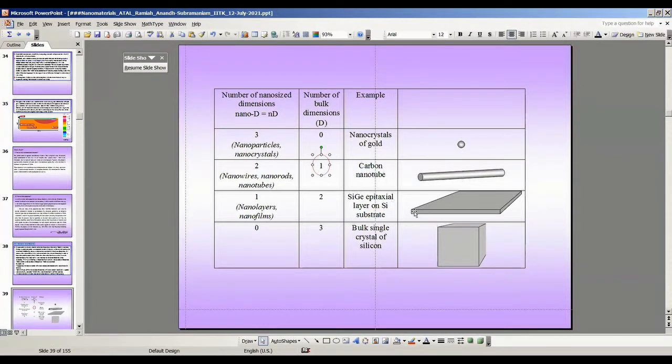But sometimes if you take a carbon nanotube and even reduce the length to a few tens of nanometers, then you will observe very interesting properties, something known as ballistic transport. That means that in normal materials, because of impurity scattering and thermal scattering, there is some resistivity, right? Now in this carbon nanotube, there may be no resistivity and the electron can travel without getting scattered. And this is called ballistic transport across the carbon nanotube.